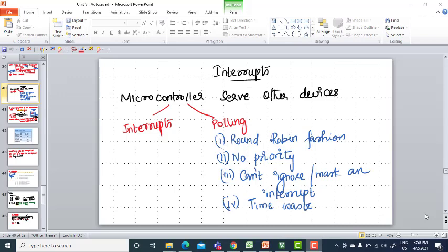Generated a square waveform by using timer. In that, what you have done is you are continuously monitoring the timer overflow flag. Why are we going to monitor? To see whether the count related operation is over or not, right?